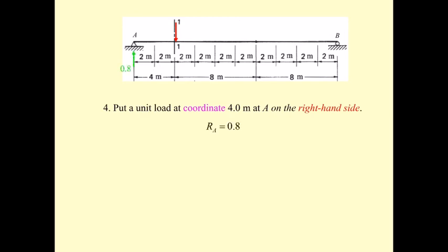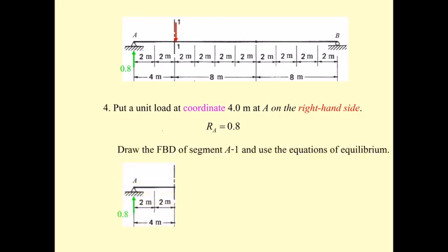You go to the previous example. And then what you have, the free body diagram now, the 1.0 just gone away. And then you have the shear and the moment. You do the same thing. Summation of the force equal to 0. So V1-1 downward is equal to 0.8.